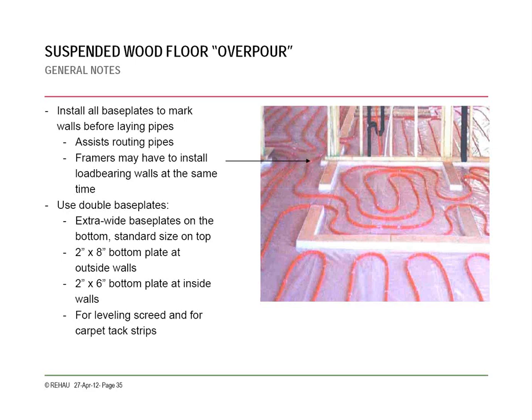If you have the luxury of knowing that you're doing this ahead of time when they're building the house, you want to put in an extra base plate, a size larger, so that you'll have nailing marks for carpet or flooring, whatever it is, against all the edges, and you'll still have your base plate on the wall after the slab is in.